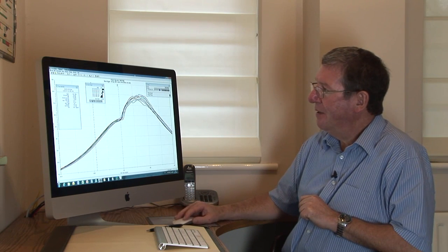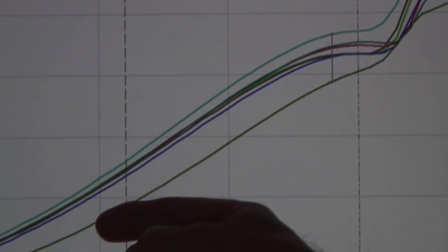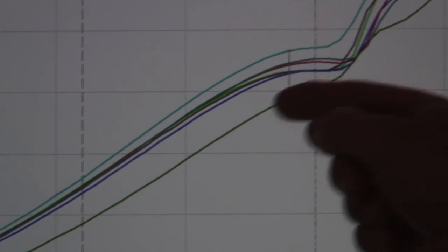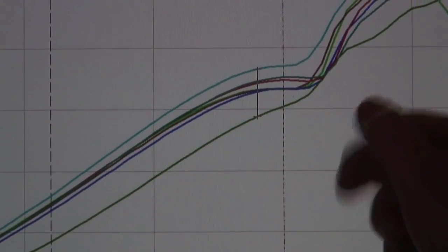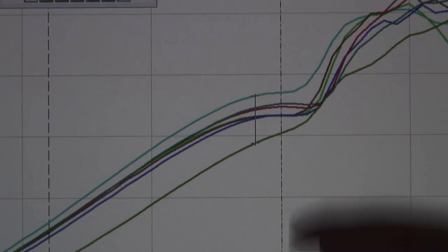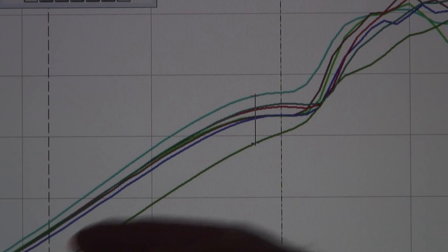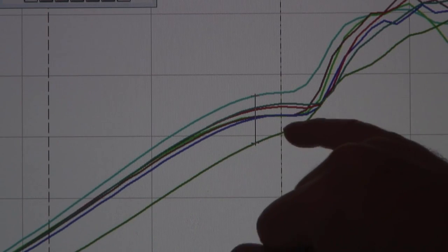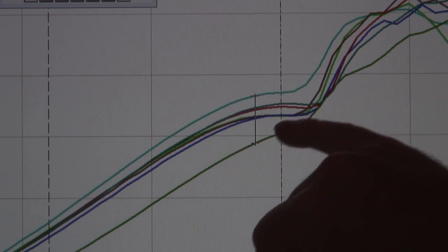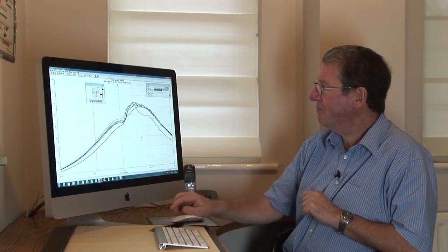On the B bank, we do the same test. We're looking for a cylinder at -20 which has risen up compared to other cylinders by the time we come to the cursor position. In this case, the cylinder that is very, very low in compression, in fact, is starting to catch other cylinders up in this area. That indicates strongly that there is pre-ignition on that cylinder.